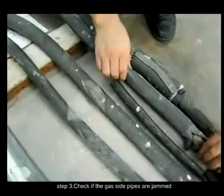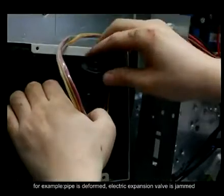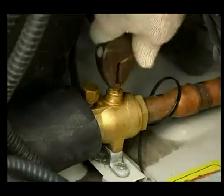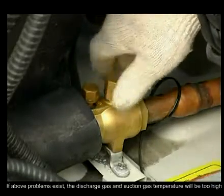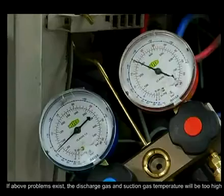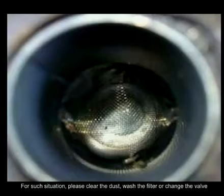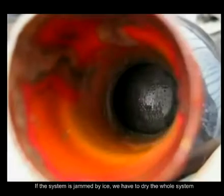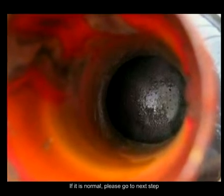Step 3. Check if the gas side pipes are jammed. For example, the pipe is deformed, the electric expansion valve is jammed, the low pressure ball valve is not open, or the filter is jammed, and so on. If the above problem exists, the discharge gas and suction gas temperature will be too high, the low pressure and current will be too low, and the suction pipe may be frosted. For such a situation, please clear the dust, wash the filter, or change the valve. If the system is jammed by ice, we have to dry the whole system. If it is normal, please go to the next step.